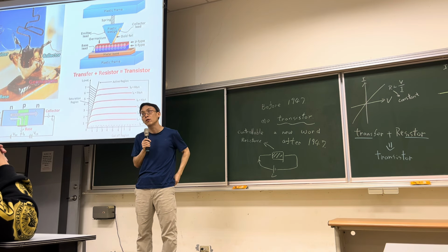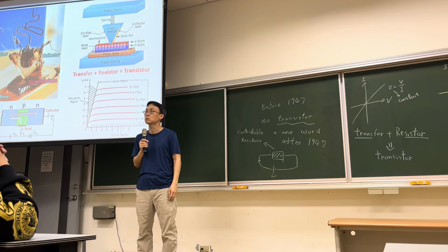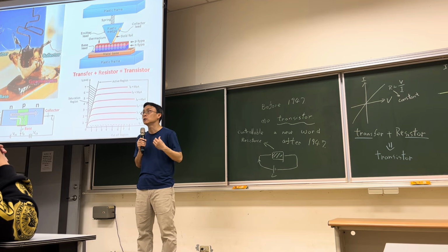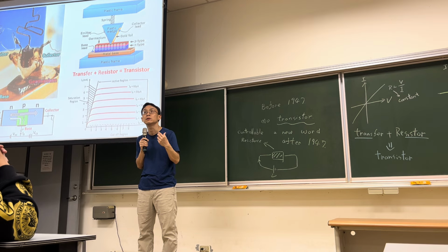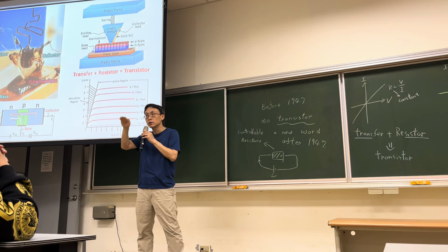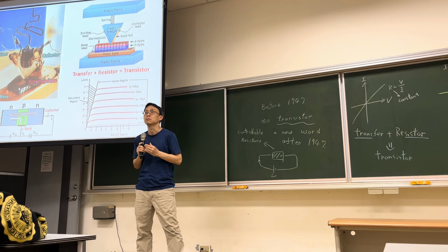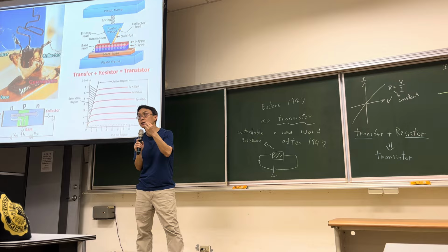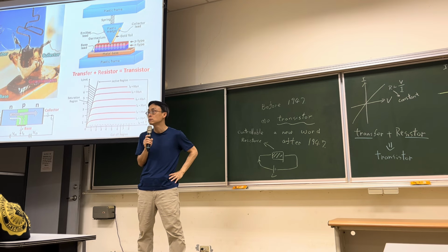Do you know what the difference is? Although both of them are semiconductors. The problem of silicon is that silicon easily oxidizes with air. So it's not pure silicon on the surface. Once you have a thin layer of silicon dioxide on the surface, that thin layer, SiO2, is an insulator. An insulator makes the resistance very difficult to change, right?